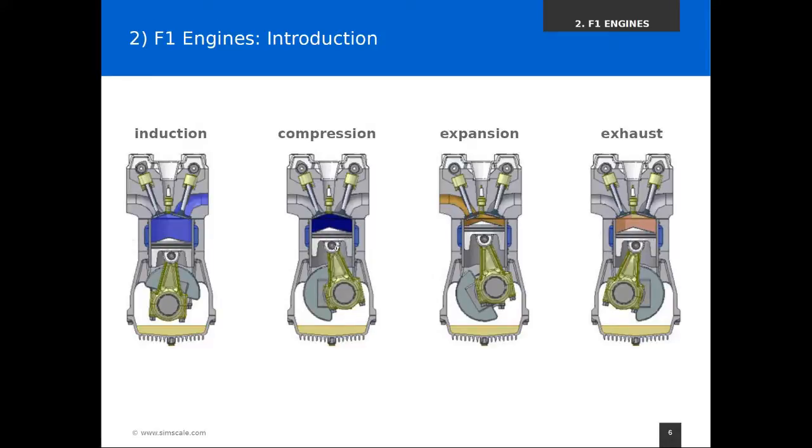And the piston is pushed up. This pushing movement comes from the rotation of the crankshaft, which pushes the piston upwards. And this is why it's called compression. This air and fuel mixture gets compressed, its volume decreases, and its pressure increases. You should already try to keep that in mind, because we'll be talking about this in a few minutes. Again, the pressure increases and the volume decreases. So pressure and volume, increase, decrease. I think you're getting the idea.